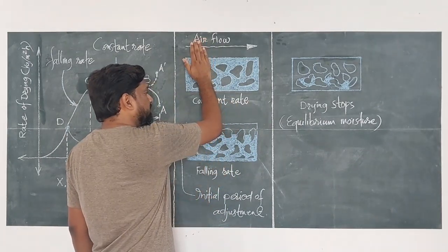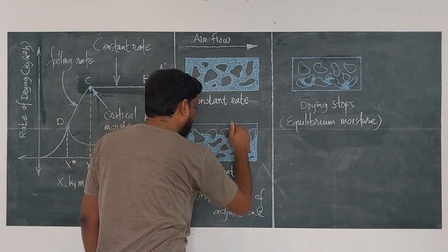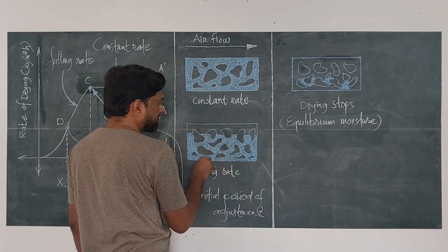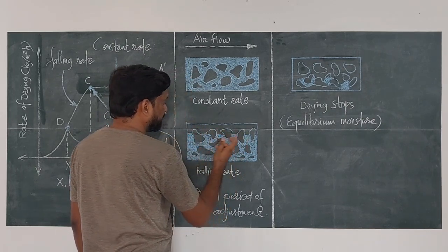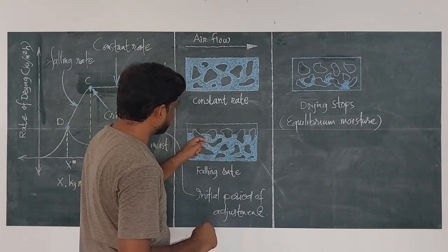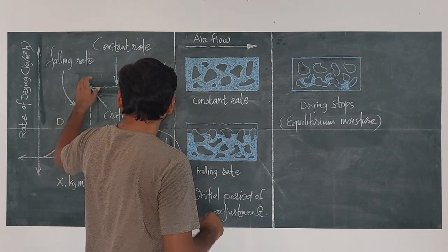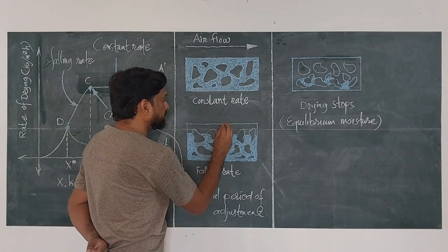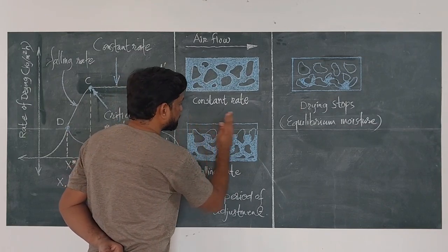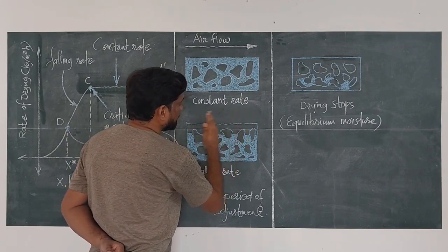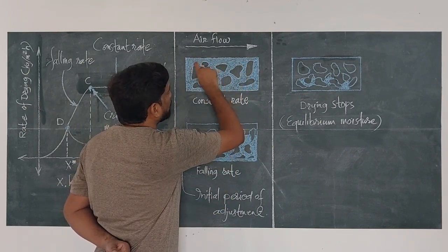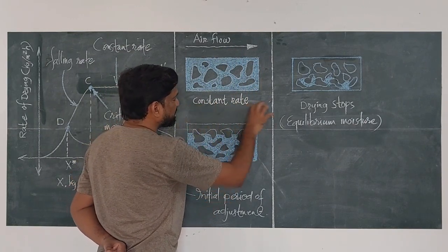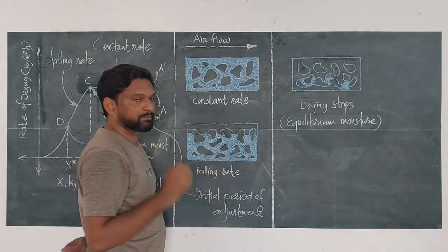The initial water is evaporated. Now the water well inside the material, which is trapped in the capillaries or the interstices of the wet material, will evaporate in subsequent drying along the curve CD. The vapors will accumulate at the space which is left by this thin film of water after evaporation. So the vapor film resistance and the gas film resistance, both the resistances are there.